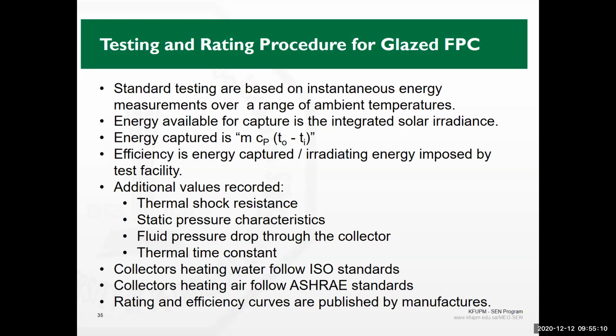Energy available for capture is the integrated solar irradiance. The energy captured and made use of is m Cp into delta T, T naught minus Ti, the outlet temperature of the collector minus the inlet temperature to the collector. This is basically how much energy has been transmitted to the fluid that is being heated. So the efficiency is essentially how much energy you are capturing divided by how much irradiating energy is imposed by